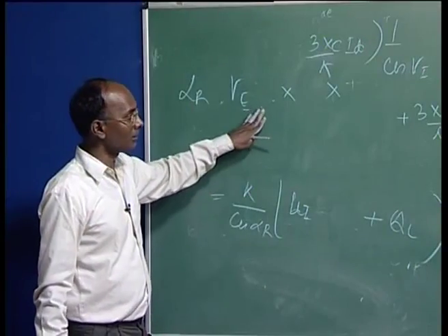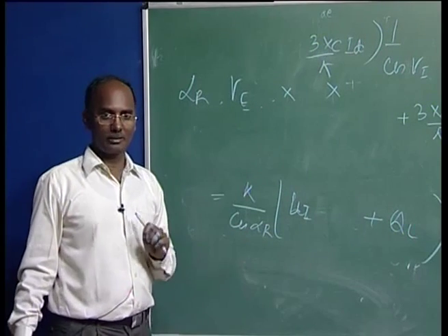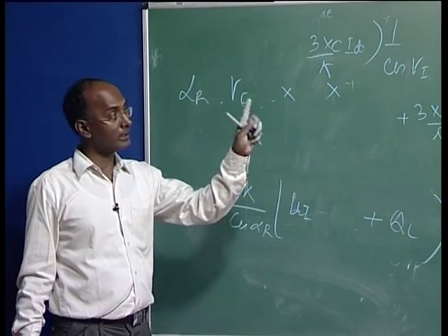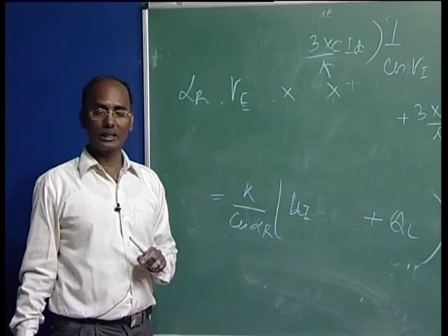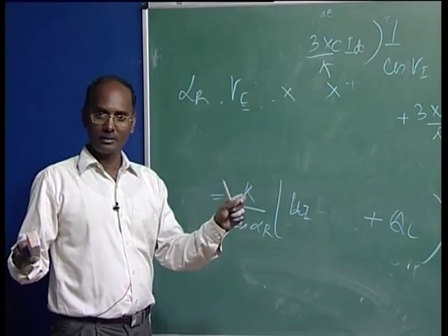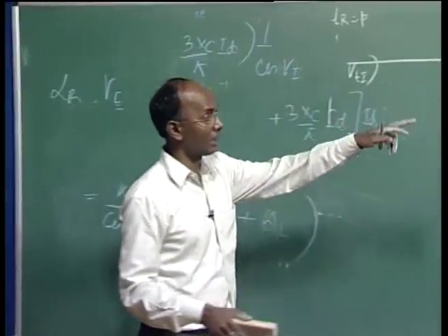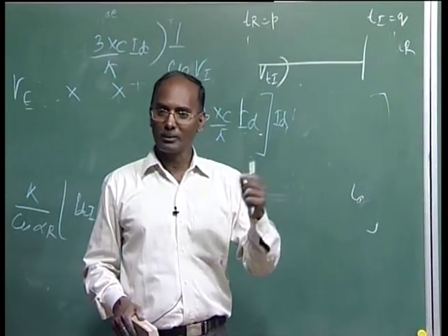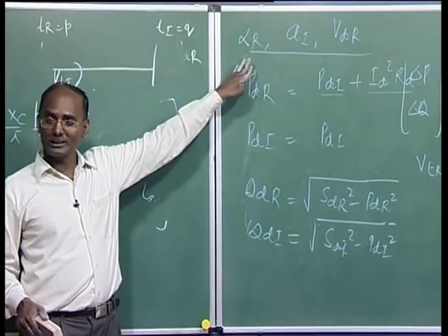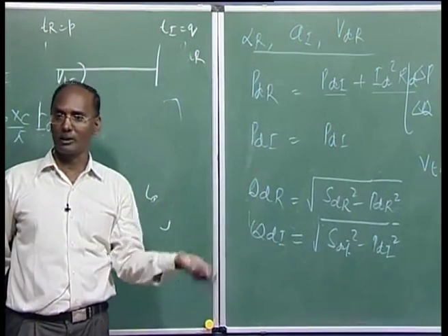Now, what is the check we normally do in this case? Even though we are not checking any of the DC variables here for violation, once you calculate VTR and VTI, based on them you can calculate the DC variables. And once a limit is hit, then you can modify again. Otherwise you may not get a converged solution.